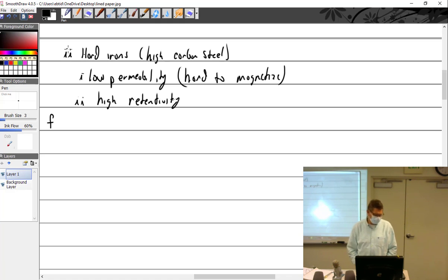So rudely interrupted. Breaking in a new engine. So you get these iron filings. I want them to be carried off with the oil into the oil filter. Now I don't want them sticking to the crankshaft and eating up the crankshaft. So I want to get rid of them. So it's really important to demagnetize these things. Like I said, we will talk about demagnetizing, but in case I don't have this written down, demagnetizing actually gets down to a point where you're supposed to store the crankshaft, long pieces, in an east-west, not north-south, because it'll start picking up magnetism from the earth and remagnetizing itself.